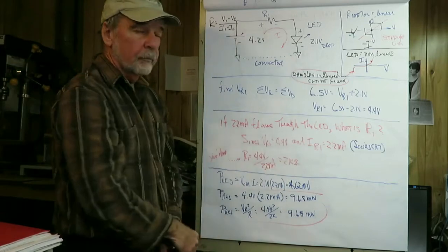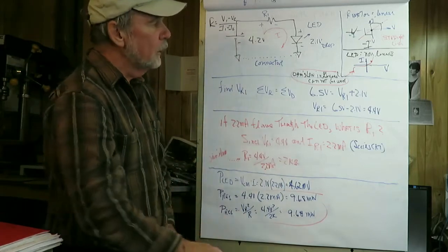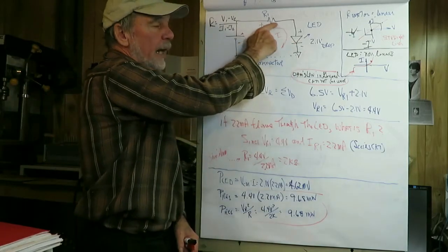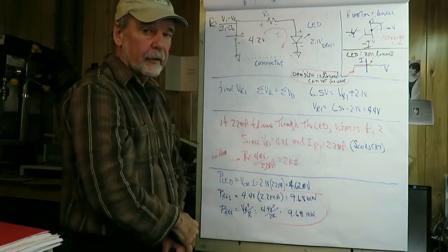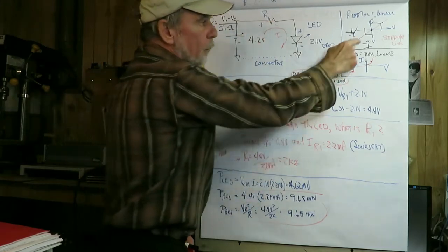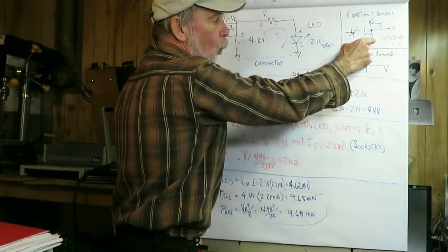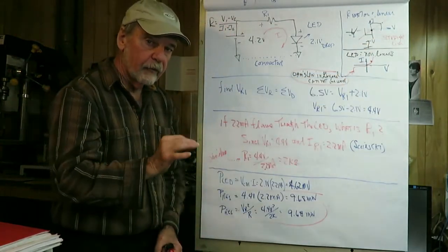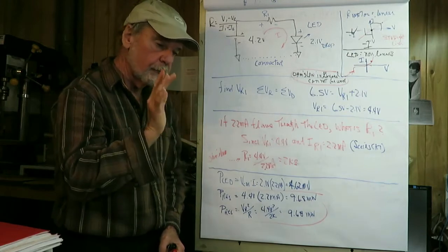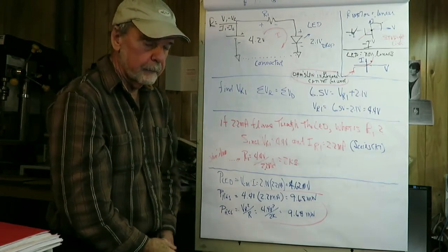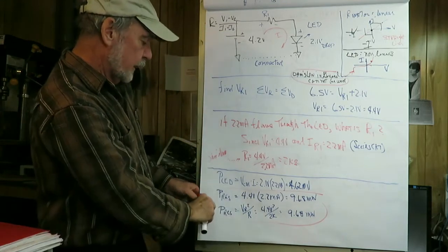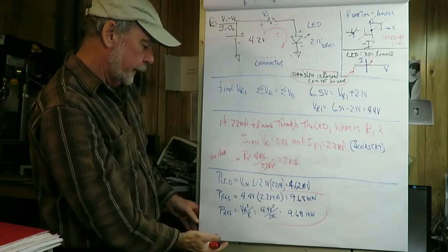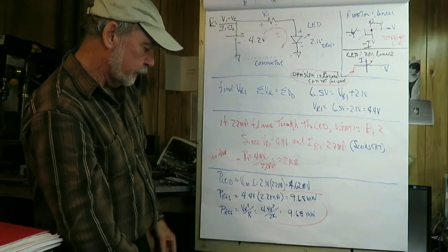2.2 milliamperes. Now, while I'm here, light-emitting diodes have to have something limiting current. Why? Because the curve goes way up high on current. And if a light-emitting diode ever starts to change color, flip the switch off. It's overheating.